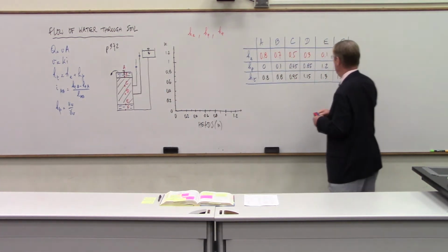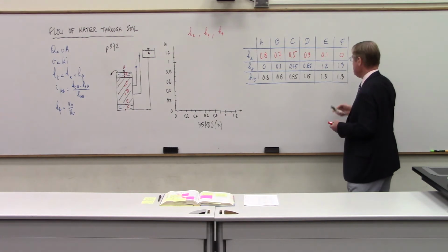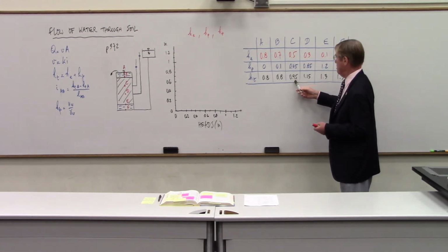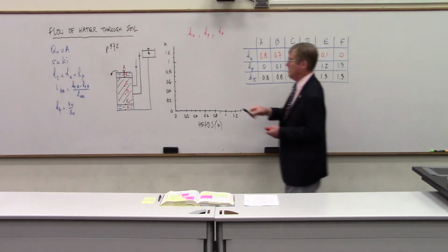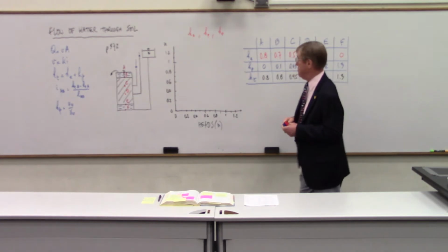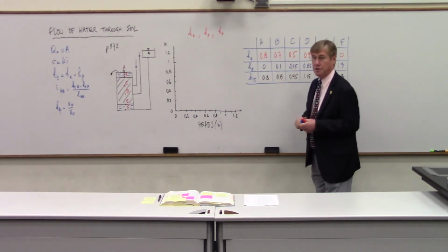We talked about the seepage force before, and you can see it here. It loses energy, 1.15, 0.95, 0.8. And from B to A, it doesn't lose energy because there's nothing in the way. So 0.8 and then 0.8.